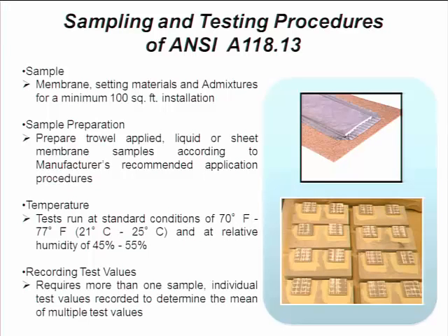To begin with, they need to bring in a sample of their product and do a sample preparation. Now, all of these specifications require the same uniform treatment of the test so that the results are comparable. If you look at the sample preparation, as we see on the diagram on the right, a sample is prepared with the exact membrane and setting material that you are going to use in the procedure that you are going to test. You prepare the samples, and all samples are tested under the same conditions in reference to the environment.